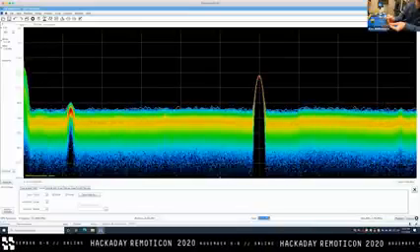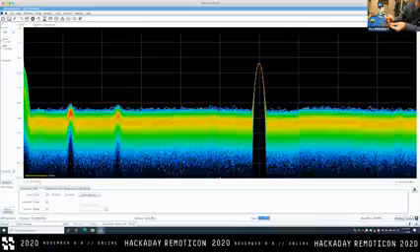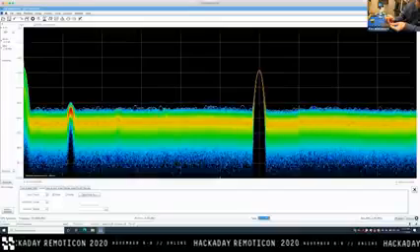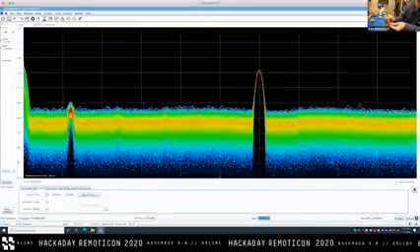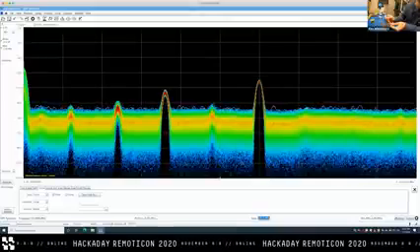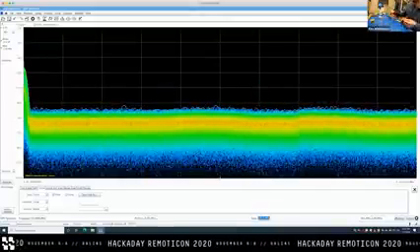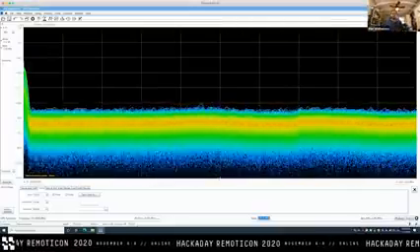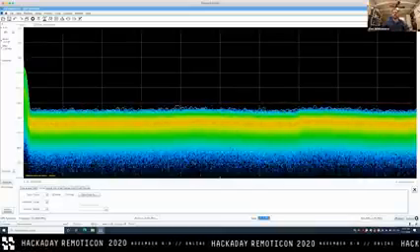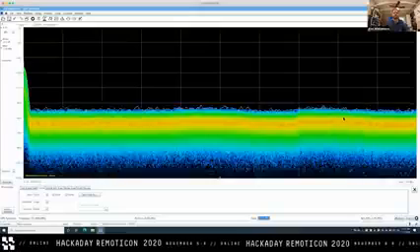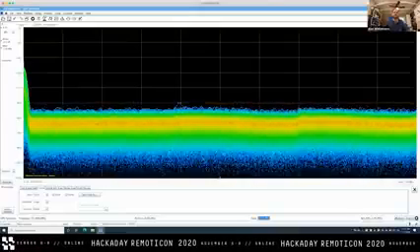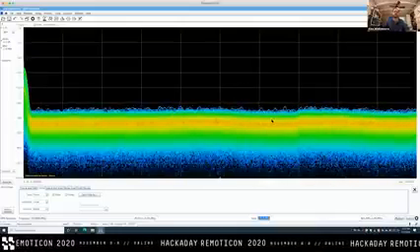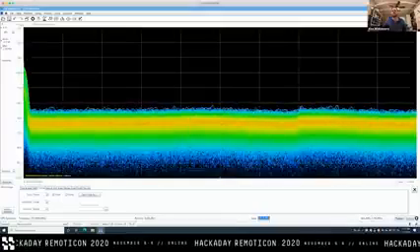But this gives us a much more interesting idea of, if I go over here and measure, let's say that 60 megahertz thing, what's actually happening on that signal, where the peak that we were measuring earlier is very indicative of how much RF power is actually going on there. And you can see why this gives you a really good visual of what's going on if you are operating in a frequency range where you can tune to it. And we'll see later, while the other tools don't necessarily scan the frequency to give you a wider than real-time bandwidth like this, at least SDR Angel does give you this sort of digital phosphor view that can be super useful if you're looking at a range that's relatively more constrained.